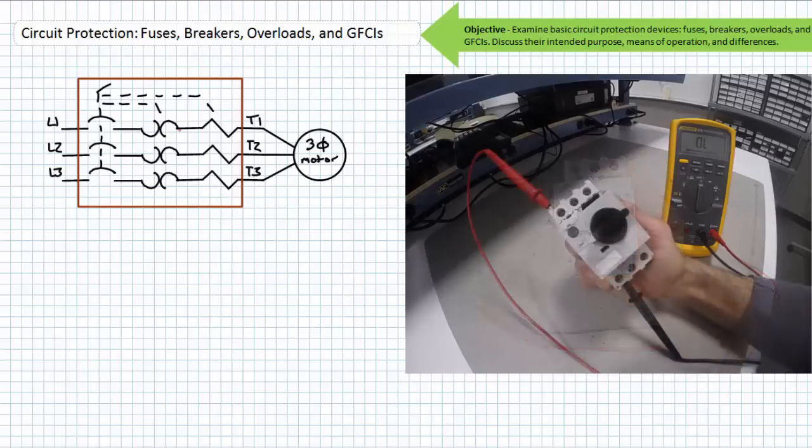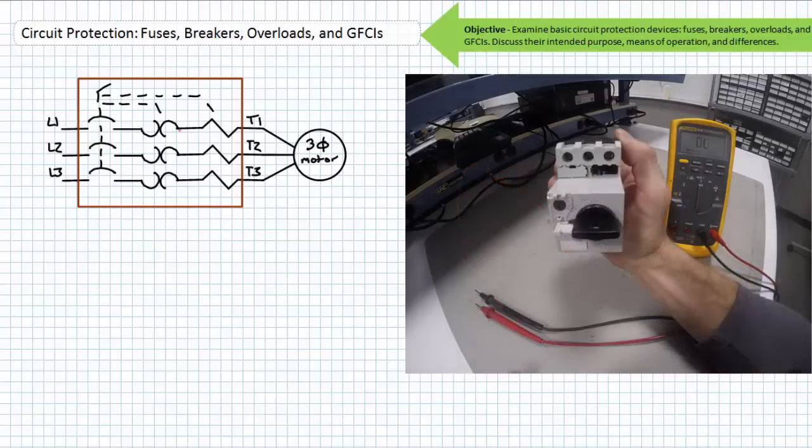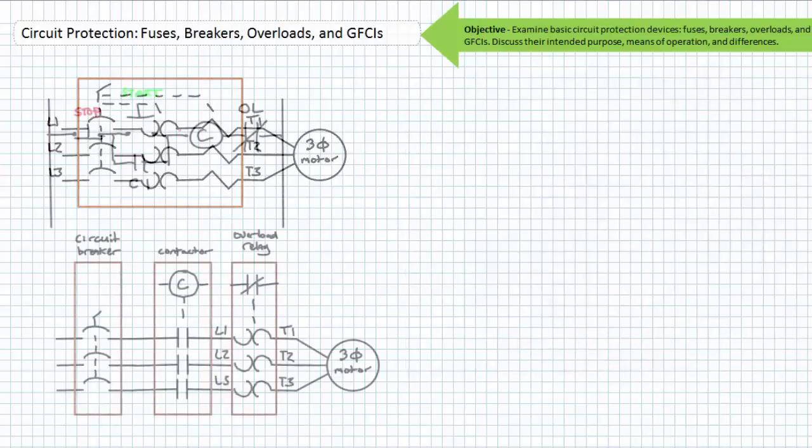all. When manually, thermally, or magnetically tripped open, an ohm meter indicates there is no connection between the L1 and the T1 terminals. When closed, an ohm meter indicates there is a connection between the L1 and T1 terminals. The manual knob can be placed in the open condition and a slider pulled out to allow a convenient method of lockout and tagout.